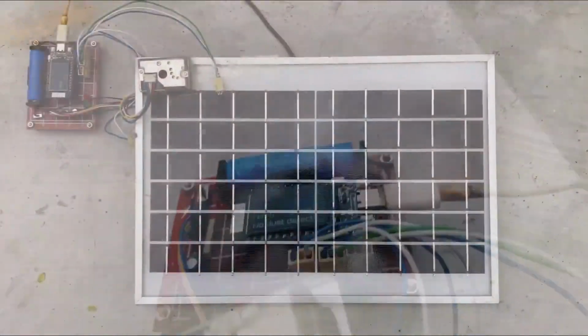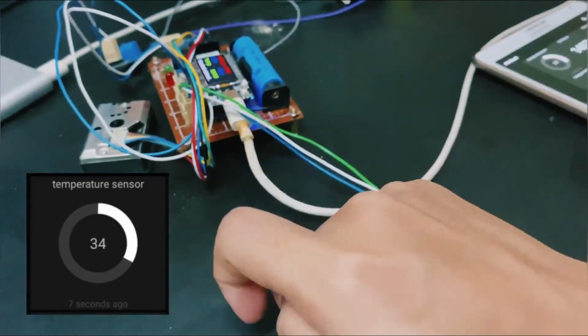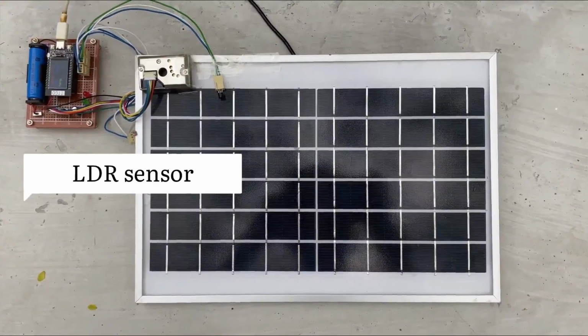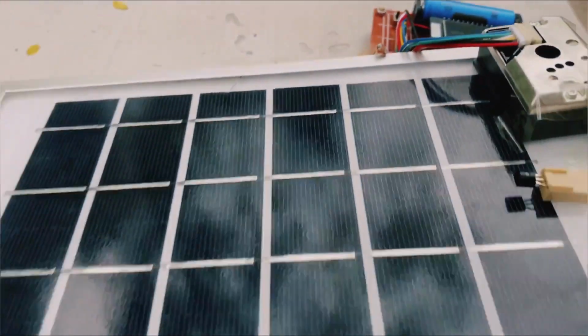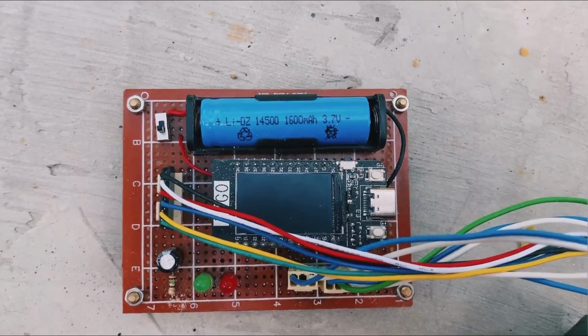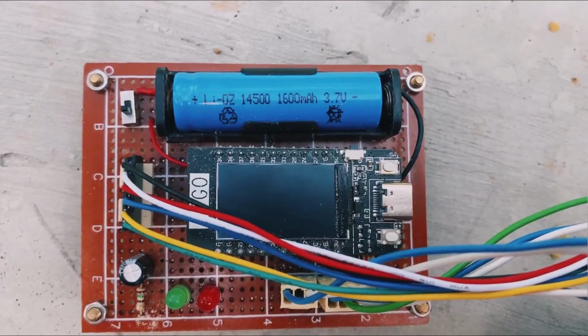Now, I will do testing on the sensors used. On the left part is the real-time update on the smartphone app. The value increased as I provided heat from my hand. The light intensity value decreased as I held my hand over the LDR sensor to block all the light from passing through the LDR sensor. So now, I will demonstrate the IoT-enabled photovoltaic monitoring system with a clean solar panel.